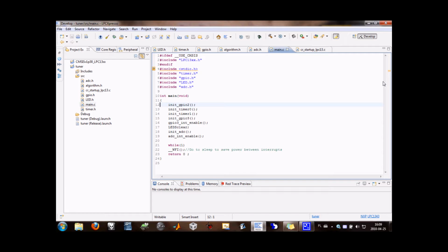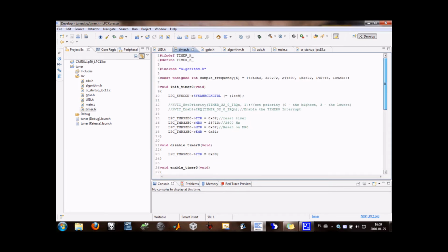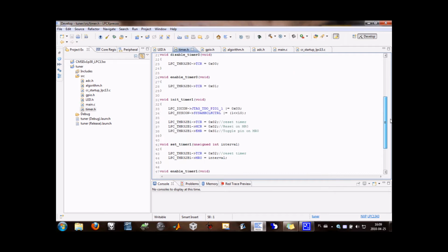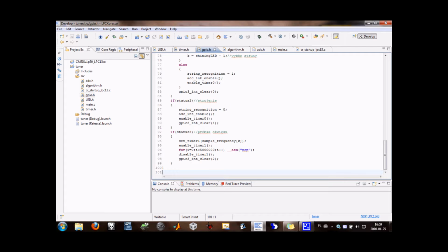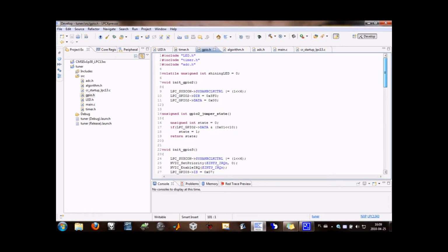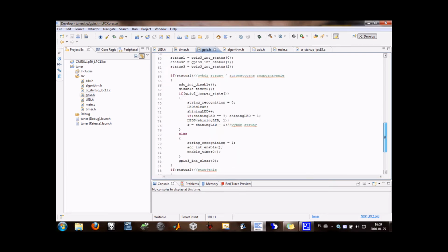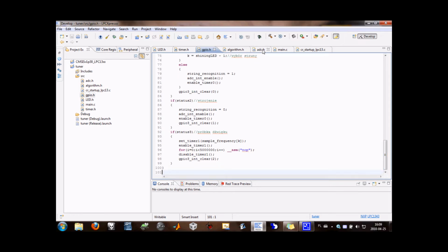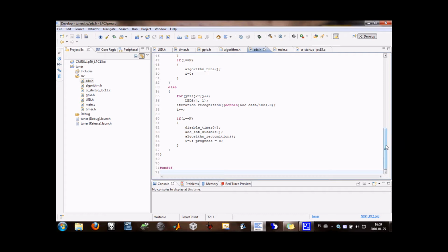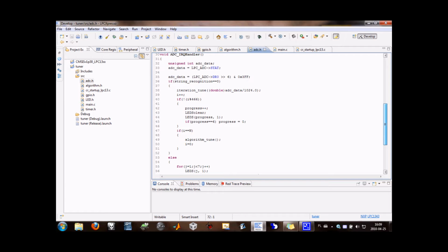What I used from the parts of this controller are 32-bit timers to trigger the AD converter interrupt and sample the signal. The second timer is used to generate a sound of proper frequency as an example. Input-output ports serve as a user interface, and the AD converter gets information about the signal.